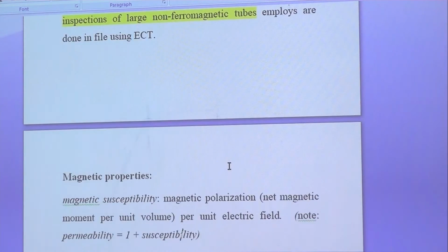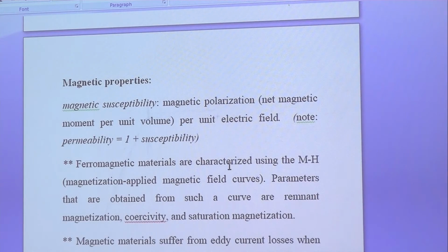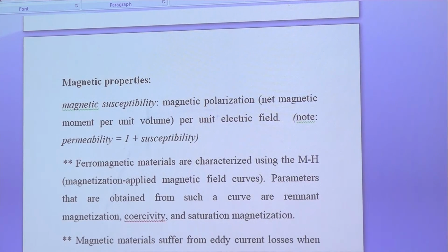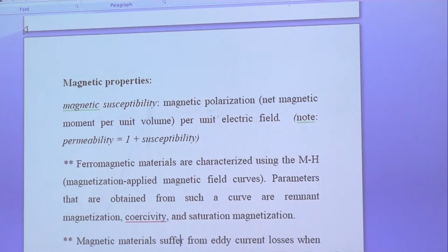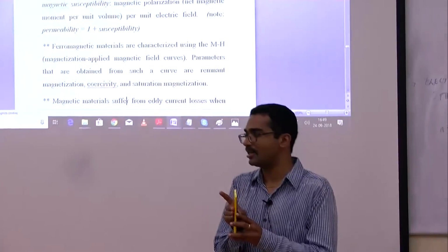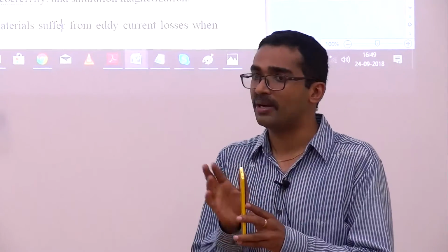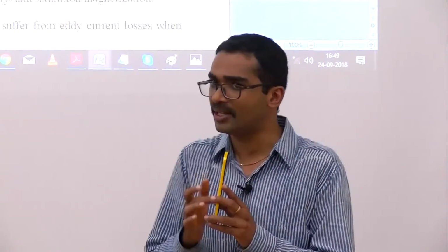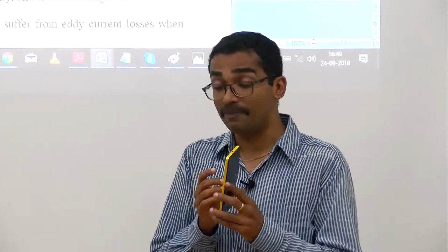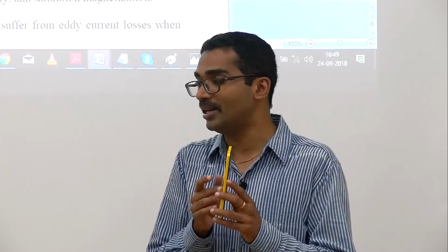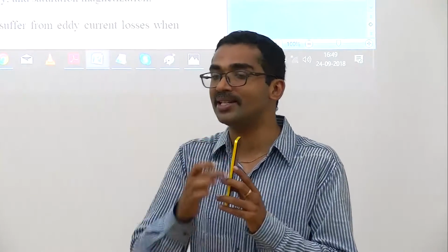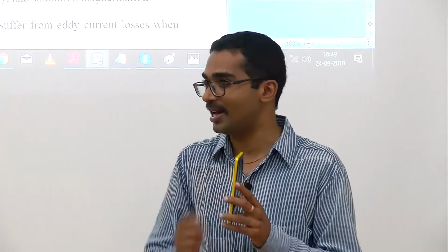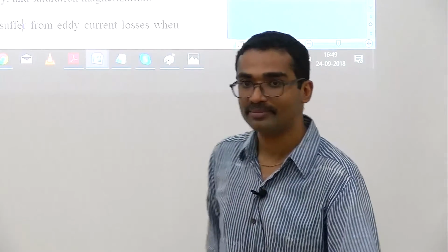And you don't need a ferromagnetic material for this. It can be any material that has some conductivity. Suppose I take this material, and let's say the surface of this is plastic, not a magnetic material. If I am changing the magnetic flux associated with it, there will be some eddy current. But because it's a resistive material, the eddy current loop will be very small. If I make it progressively conducting, the eddy current loops will be larger and larger. You follow? Okay.